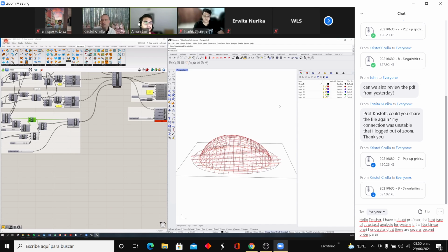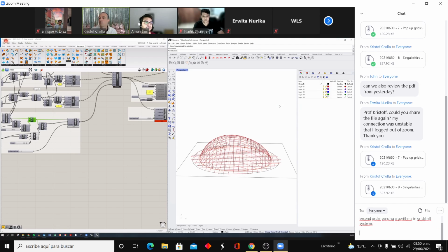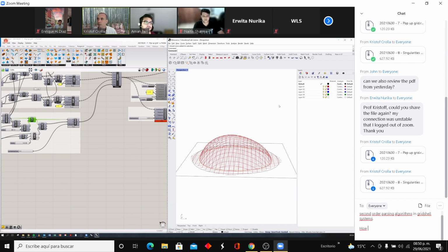Okay. With the Z coordinate fixation, you need to be very careful, because if you lock something in the XY direction, then automatically the minute something moves up or down, your lengths will change. So you will create a setup where the balanced equilibrium will incline towards a change of length. And it's a change of length that with a rigid equidistant grid becomes quite difficult. That's when you have tension concentration that will break the grid. Does that answer?